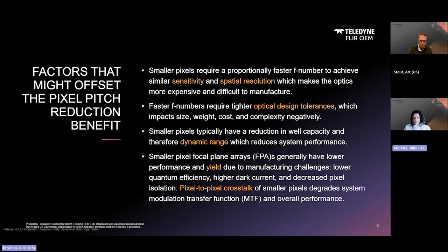Higher temperature operation is beneficial for power, readiness time, and reliability of our coolers. So similarly, isolation of smaller pixels is more challenging. As the pitch to diffusion length ratio decreases, the fabrication processes become more challenging. The resulting pixel-to-pixel crosstalk is often degraded. So spatial crosstalk and residual fixed pattern noise impact range performance.